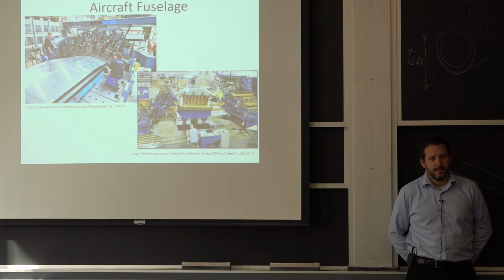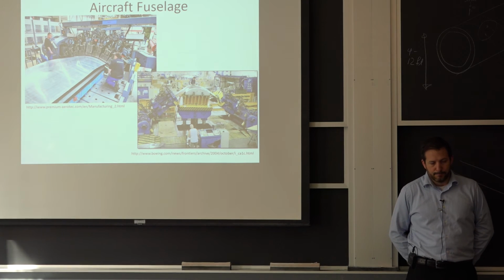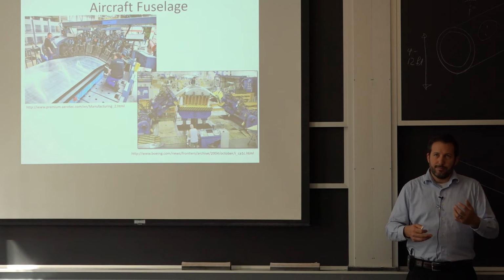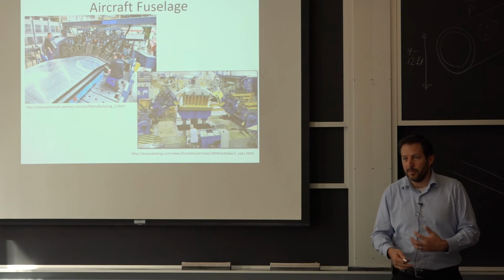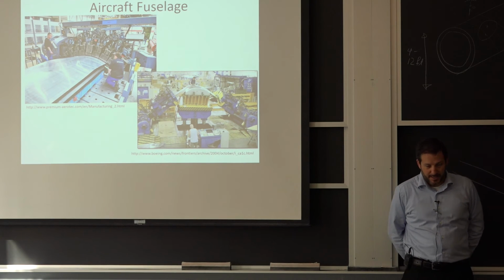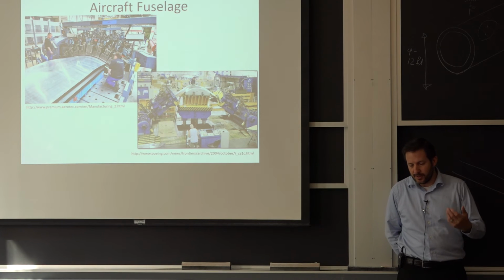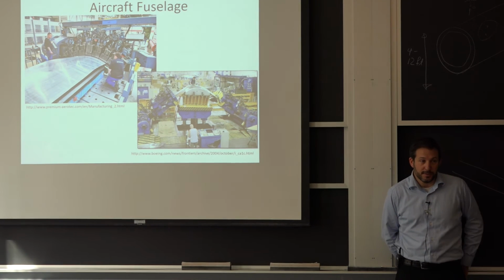That makes sense? Why you do it? There's another advantage of doing it, which is when you create that 2% strain, you sort of prepare the microstructure for a heat treatment. So a lot of things kind of go hand in hand. By deforming it, you get the aluminum to make the strengthening precipitates that you needed to create.